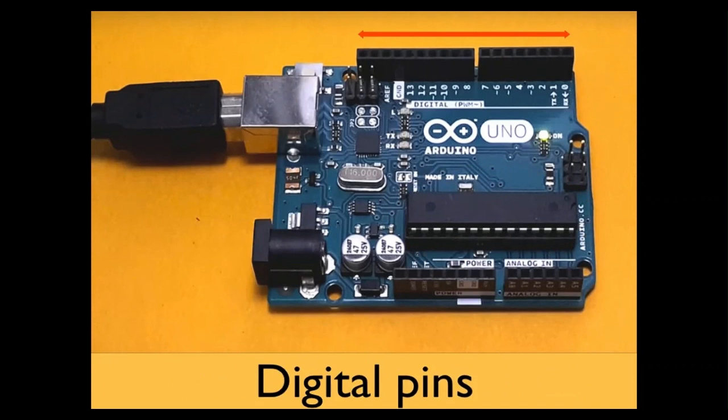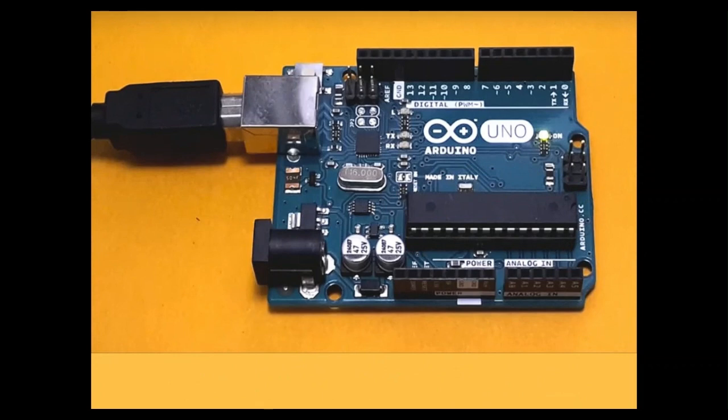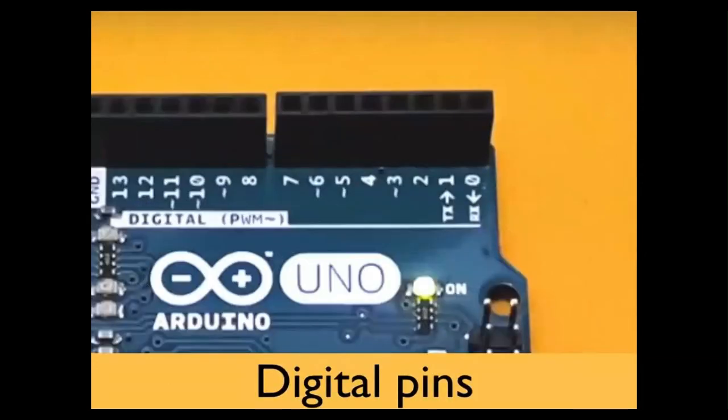These are digital pins. Each of these can be programmed as either an input or output. Digital means they can be on or off, high or low. For example, to dim an LED, to generate audio signals, etc. The pin number 0 and 1 can be used for serial communication with other devices.